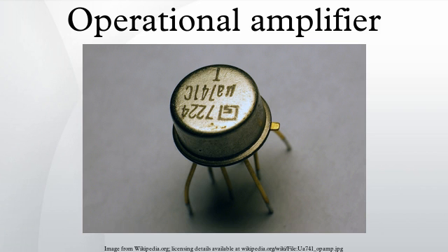In these cases, the feedback circuit can be stabilized by means of frequency compensation, which increases the gain or phase margin of the open-loop circuit. The circuit designer can implement this compensation externally with a separate circuit component. Alternatively, the compensation can be implemented within the operational amplifier with the addition of a dominant pole that sufficiently attenuates the high-frequency gain of the operational amplifier. The location of this pole may be fixed internally by the manufacturer or configured by the circuit designer using methods specific to the op-amp. In general, dominant pole frequency compensation reduces the bandwidth of the op-amp even further.